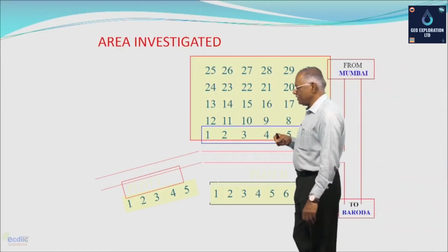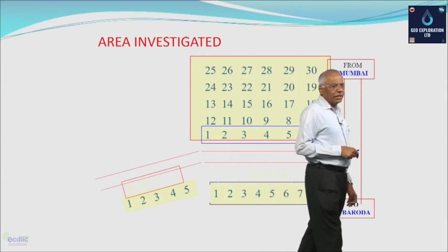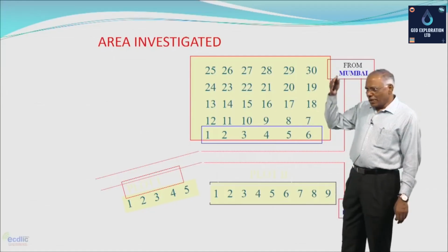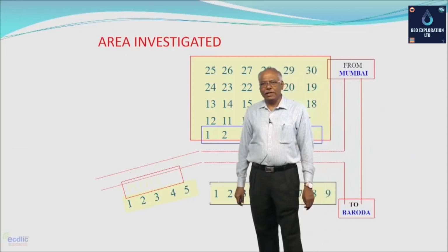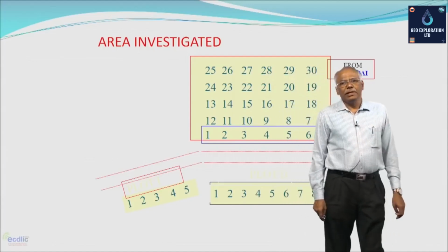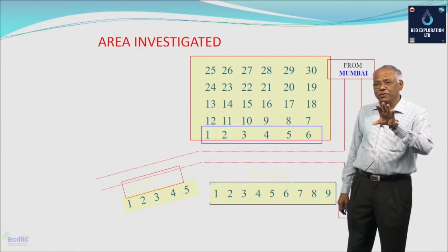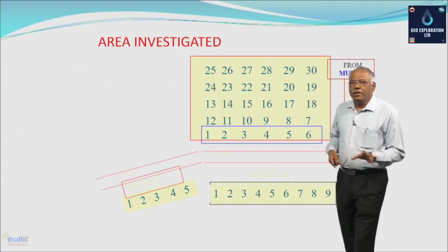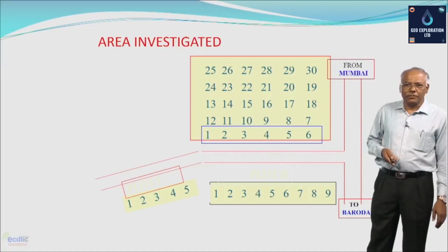In case of searching for the groundwater resource, electrical resistivity lows are the target areas, from the point of view of finding out vertical variation in the subsurface by using the vertical electrical sounding technique. This grid pattern is very important for locating the electrical resistivity low, which is a likely area from the point of view of occurrence of the groundwater. This grid pattern is very important by considering the horizontal profiling.